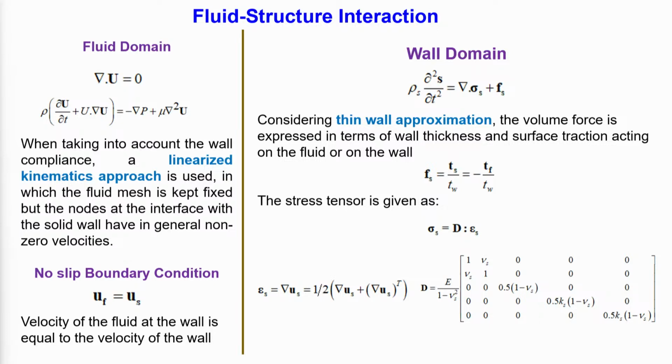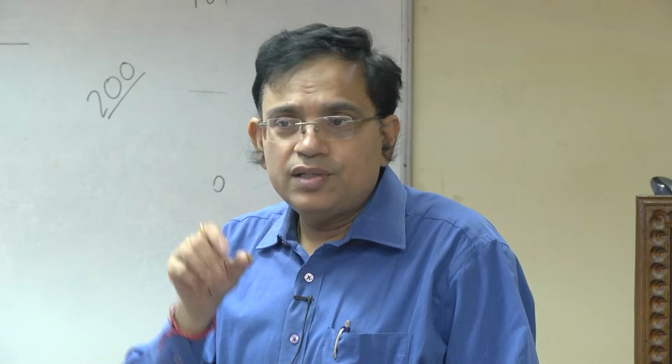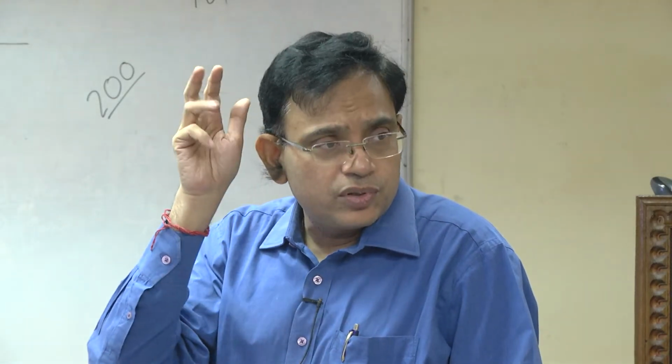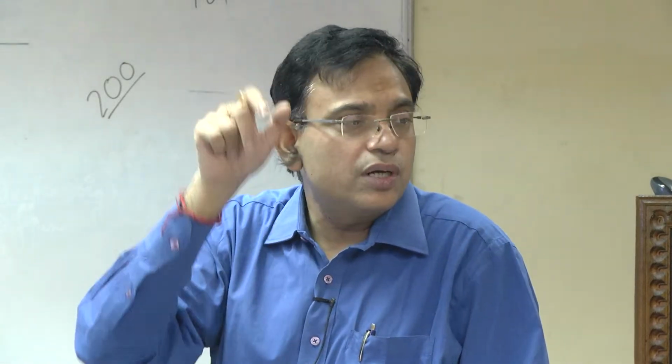You may argue that blood is a non-Newtonian fluid, so why Newton's law of viscosity? For large arteries that approximation is not that bad. So, always keep in mind that for large arteries it is the elasticity of the artery that should be your main concern, and for the small blood vessels it is the non-Newtonian nature of the blood.